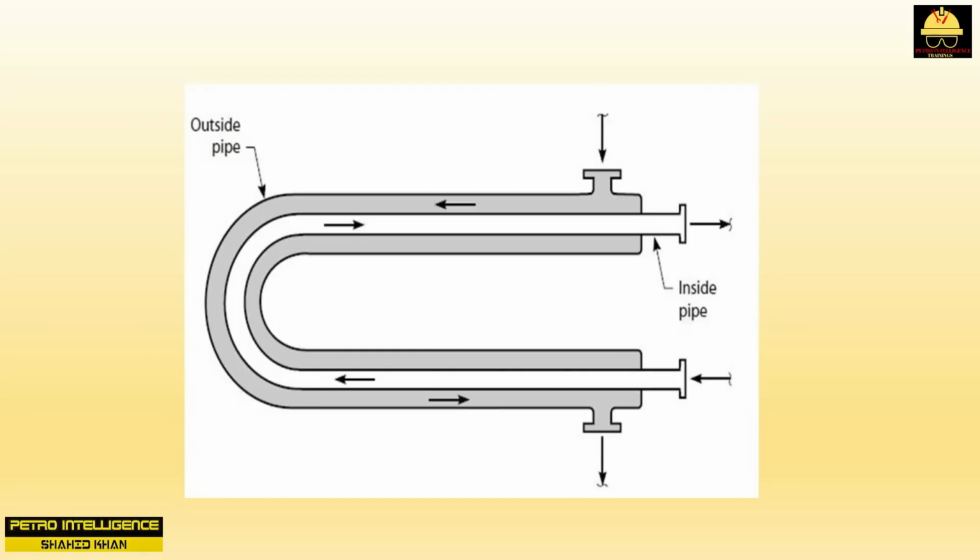Double pipe exchangers. Also called hairpin exchangers, the double pipe heat exchanger, as shown in picture, is the simplest of all types we have discussed. It is nothing more than two concentric pipes. The inner pipe might be 2-inch diameter and the outer pipe 3 inches. Double pipe exchangers are true countercurrent flow heat exchangers. They are rugged and are reasonably cleanable. Moreover, they are not subject to bypassing. The only problem with them is cost per square foot of heat transfer surface area.